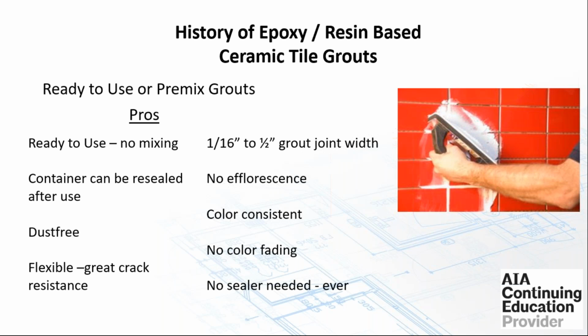The pros and cons of these ready-to-use grouts. Pros: it's ready to use, there's no mixing. So you're not adding too much water into it. You're not over mixing it. It can be used from a 1/16 of an inch up to a 1/2 inch grout joint.